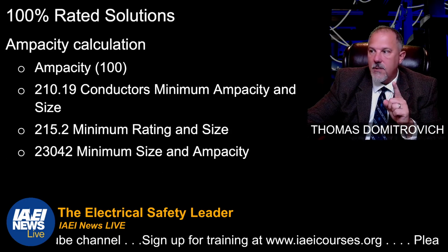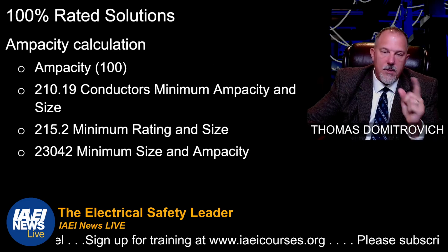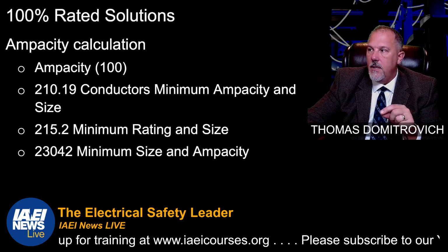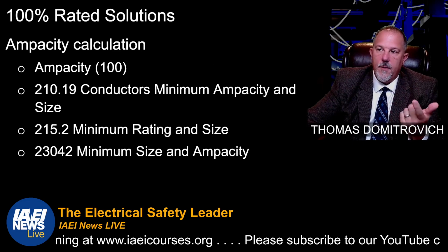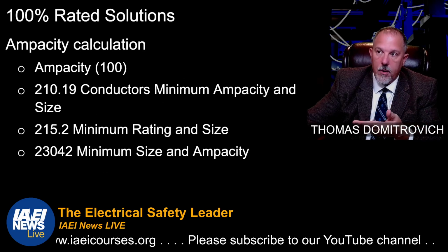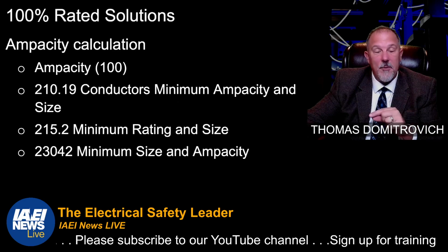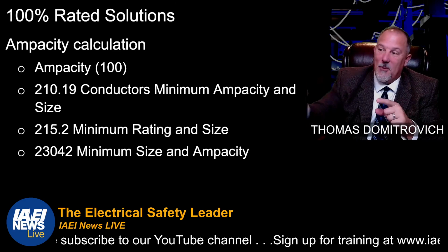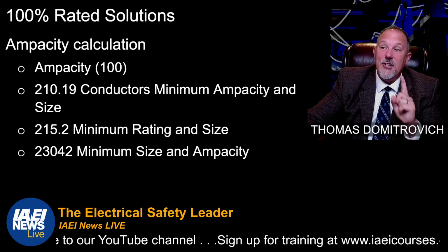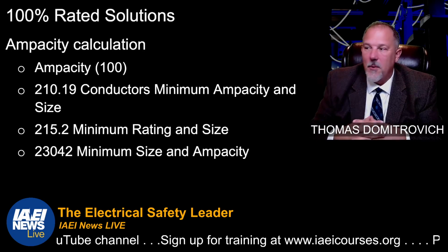So we know a continuous load is the maximum current that's going to continue for 3 hours or more. Because that's the other key thing: do you say more than 3 hours or 3 hours or more? That was the reason I went to the definition, to make sure I was using the right word.